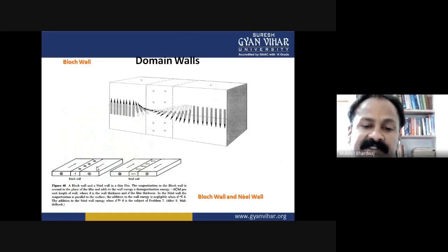With the field, this stage corresponds to the top of the magnetization curve. The model discussed above accounts successfully for all observed aspects of magnetization such as hysteresis, remnant flux density, and coercive fields in polycrystalline samples. Crystalline boundaries act as obstacles, having a variety of barrier heights to the wall movement. There is no single threshold field for the onset of irreversible motion or domain rotation, and the magnetization will have the sharp loop as shown in the figure.